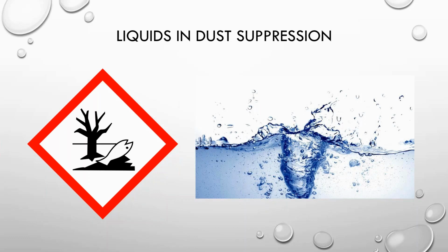Nowadays, the most common liquid used for dust suppression is, of course, water. There are some water additives available that are environmentally friendly, which can be added to make water less vulnerable to evaporation, but more often than not, pH 7-ish H2O is what is used. This is mainly due to its availability and mostly low cost, but on sites where water is metered it can become quite expensive.